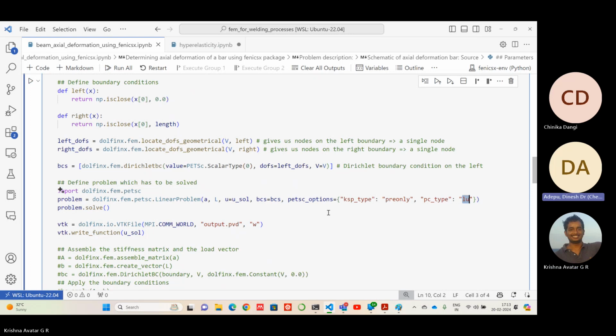So I'm just wondering, I think in one of the tutorials we should look into PETSc, like petsc4py for Python, what the linear equations are and all the ways to solve them. I actually think that would be the best way. In fact, even to discuss all these building blocks of the DOLFINx package, that would be a wonderful exercise, because we would like to know all these PETSc options as well. These PETSc options will depend on which problem we are solving and on the structure of the matrix system as well. And now finally problem.solve actually solves the problem.